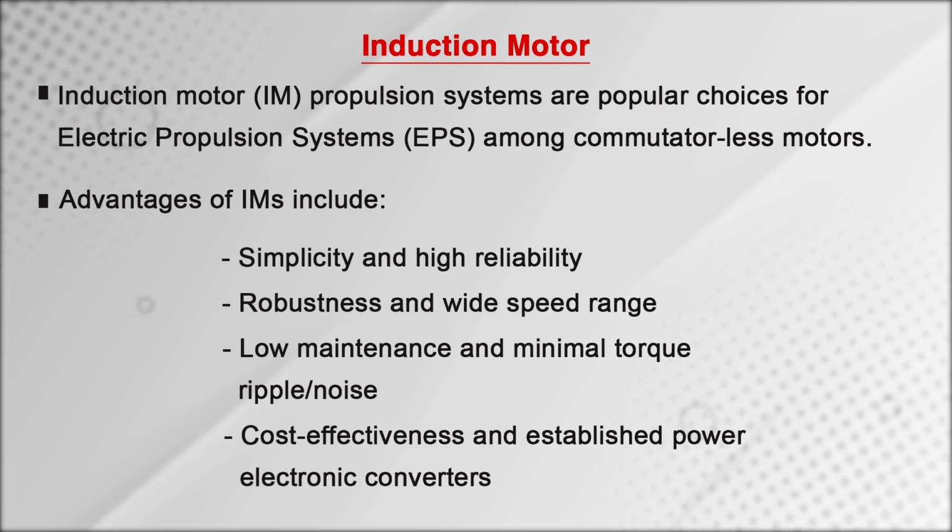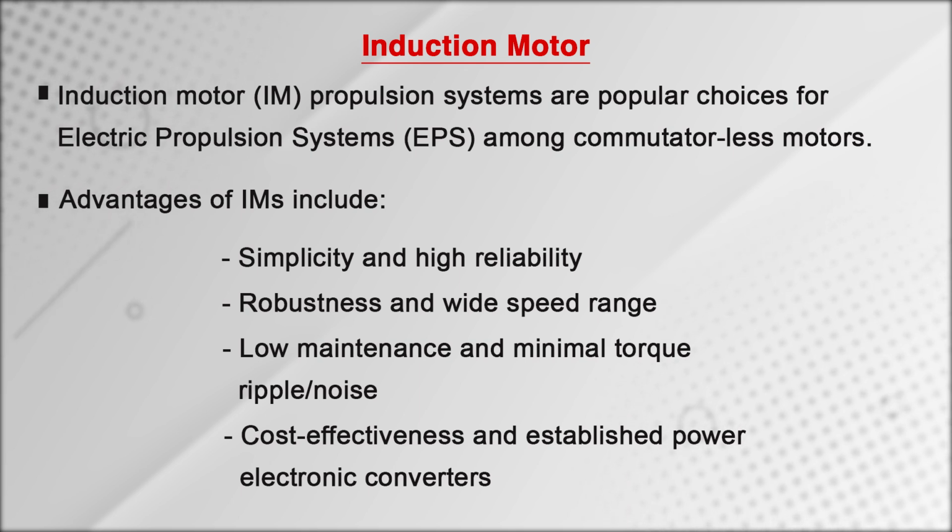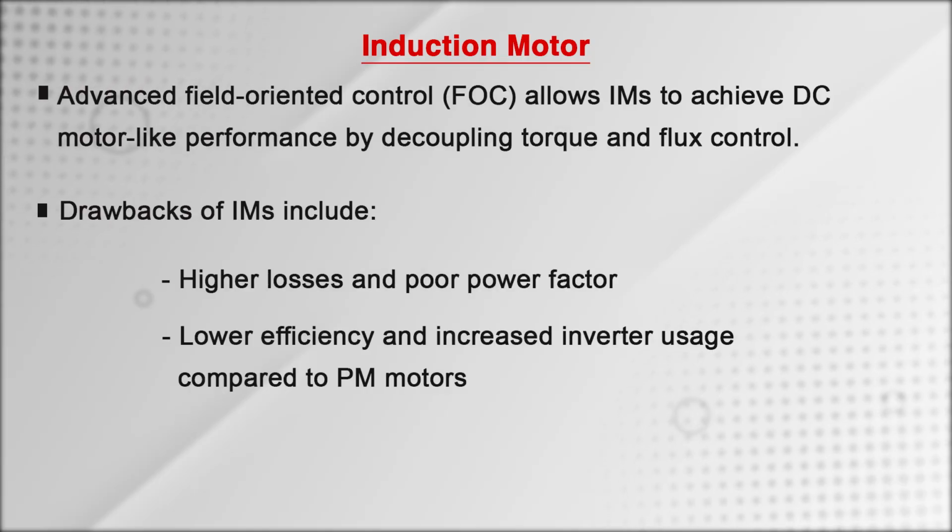They also perform well in a very hostile and harsh environment. By employing advanced control algorithms like vector control, DTC or field oriented control, induction motors can deliver performance characteristics very much similar to those delivered by a DC motor.